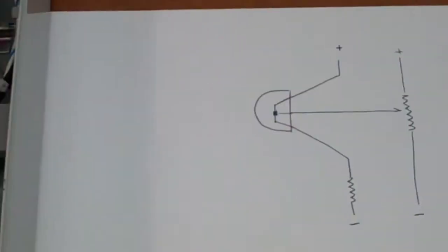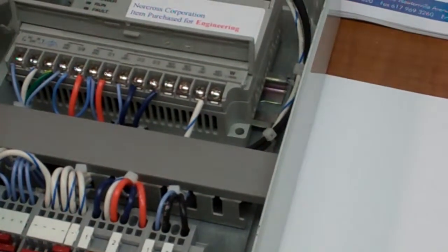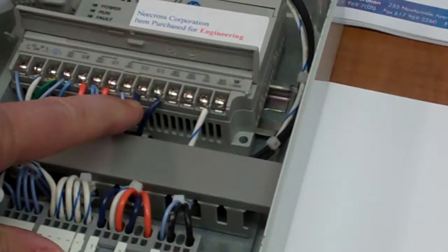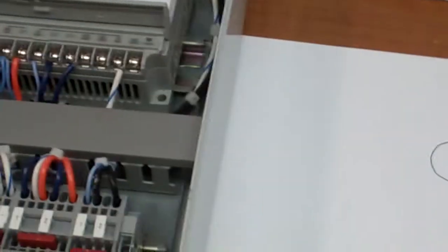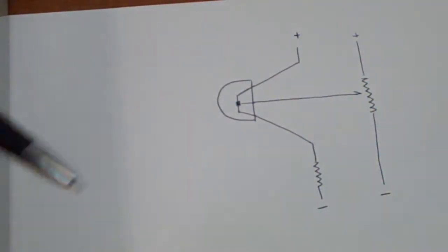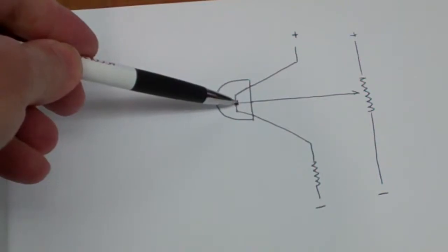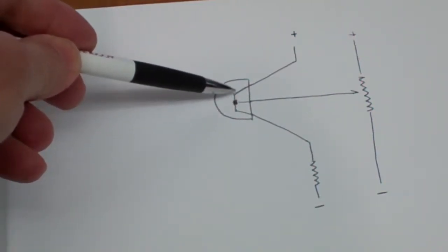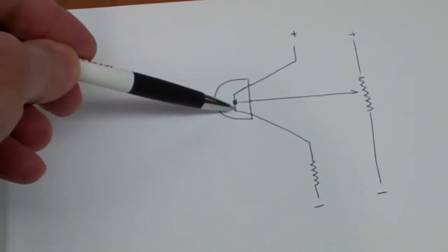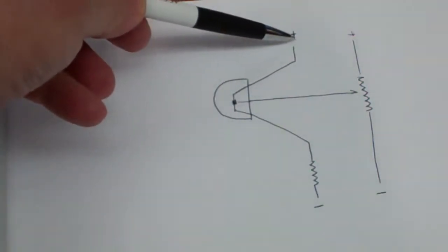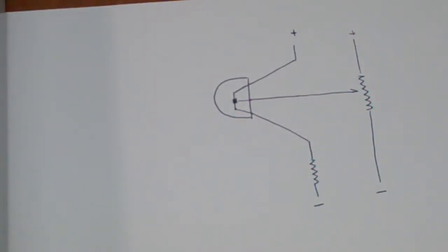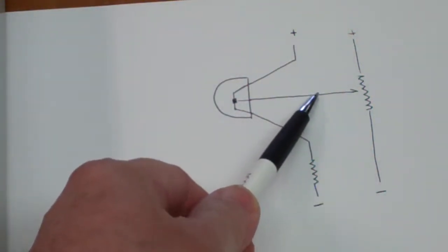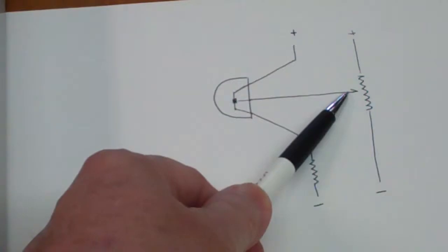We have a customer who has one of these controllers. The air valve is always on when the power is applied. This means that this piece here has shorted out, so it's just passing current all the time. So when the power is applied to the PLC, whoosh, the valve turns on. It's always on. This is where the start-stop command comes in from the PLC logic. It's not working for this customer.